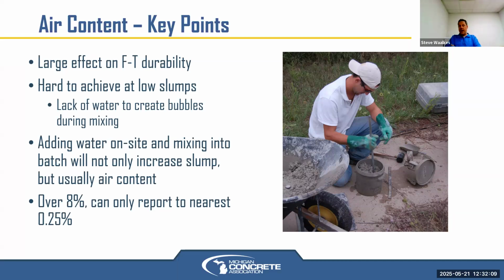There are viscosity modifiers that will tighten up the slump too. It doesn't take the water out. The water still exists in there, but it changes and kind of makes everything sticky. Those exist as well to reduce the slump if that is the concern, as long as you're not already over the water cement ratio. But again, not all specifications allow those to be used.